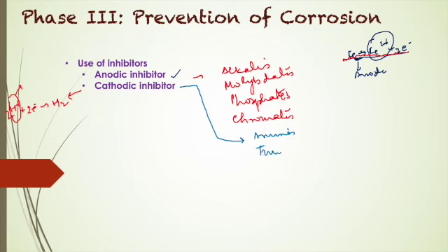So I'll write down thioureas, heavy metal soaps. They are just soap-like materials. Okay, substituted ureas, thioureas, mercaptans, they can be used as cathodic inhibitors. How do they work? They get absorbed over the cathodic material surface and act as protective layers. So if this is the cathode, they are absorbed at this portion. Okay, and they act as a protective layer.